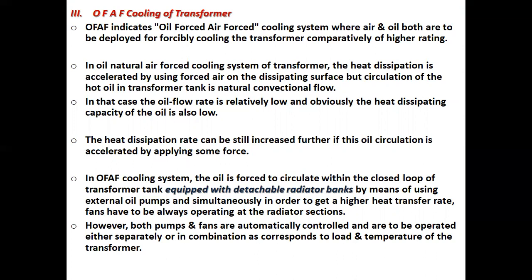In the oil natural air forced cooling system of transformer, the heat dissipation is accelerated by using forced air on the dissipating surface, but the circulation of the hot oil in the transformer tank is natural convectional flow. Again, I repeat, in the oil natural air forced cooling system, the heat dissipation is accelerated by forced air on the dissipating surface, but the circulation of hot oil in the tank is natural convectional flow.